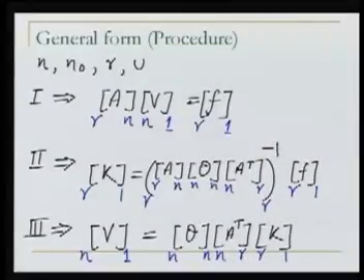Okay, now the general form. I'm going to give you the procedure for how to solve a problem by the adjustment by condition equation method. First, in whichever problem, look for the number of observations. What is the minimum number of observations which can define the problem? Then find the redundancy and how many unknowns there are.